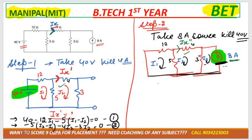Corner branch. And in the corner branch there is a flow of single current or double current? Single current. So I3 direction and 8 ampere direction is same or opposite? Opposite. So we can directly write it down as I3 is equal to minus 8 ampere. If both the directions are same, then in that case we'll need to write down I3 is equal to plus 8 ampere.